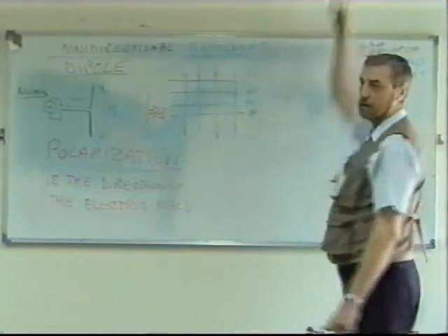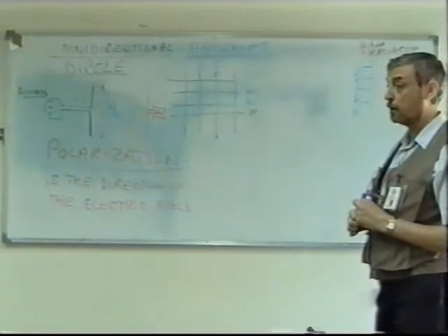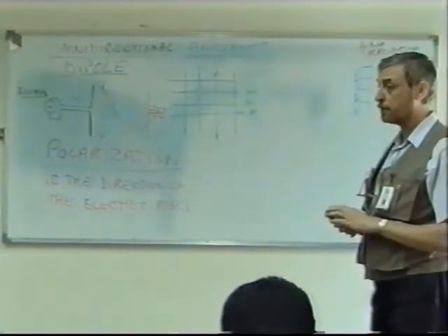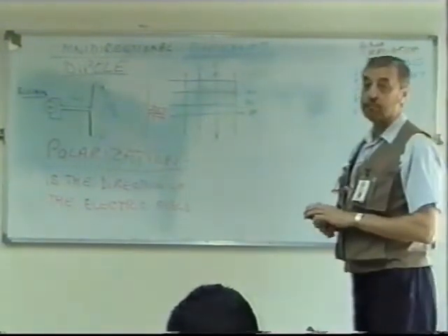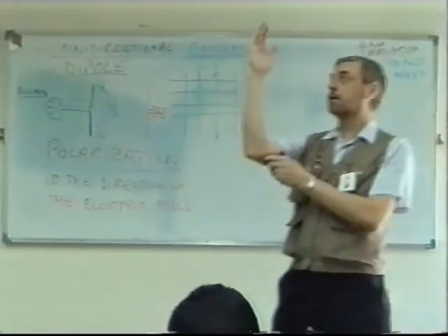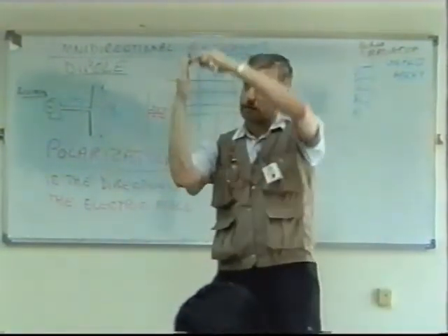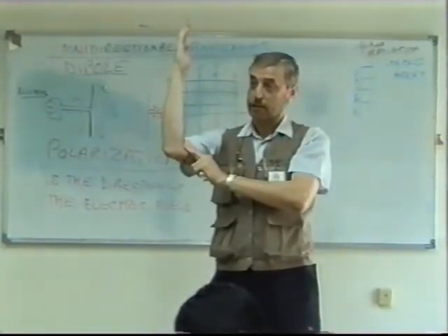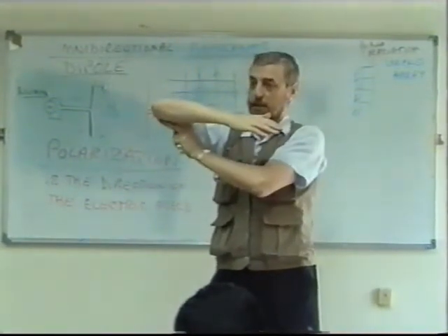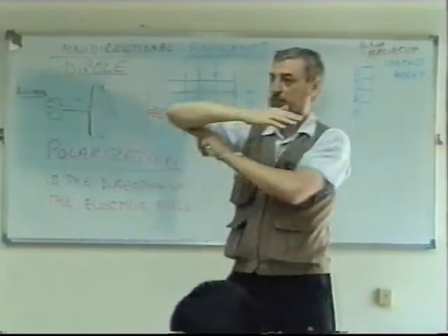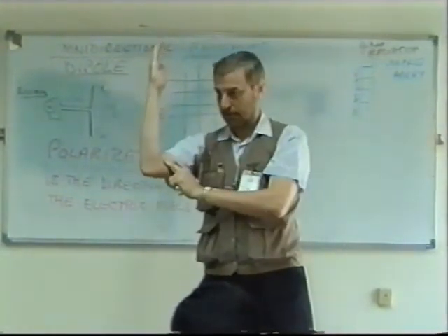Sorry? Polarization? Yes, the polarization is still vertical. The reason being, of course, that in a car, the receiver's antenna is also straight up, isn't it? Vertical. You never see a car, or you shouldn't, with its antenna like that, because as it changes direction, it might miss the signal. This is always the best way to have your antenna for the car.